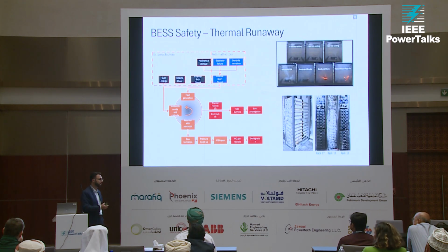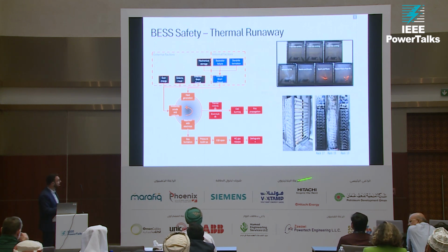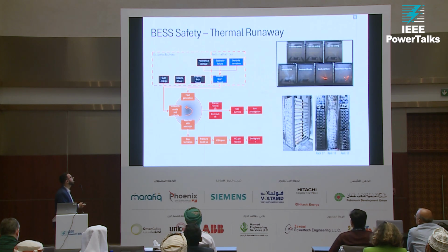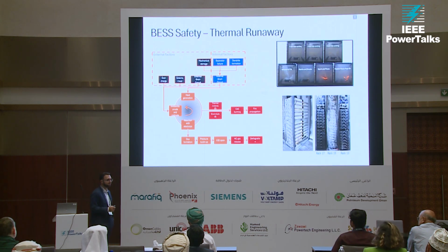There are also shipment and vibration testing, different types of testing that go into those systems. The other reasons are electrical: overcharging, over voltage, and also under voltage, but also short circuit, external short circuit. The last one is external heat. Cells can run up to 60, 70 C, so they're very forgiving when it comes down to ambient conditions. It's best to keep them in the 30 C range.